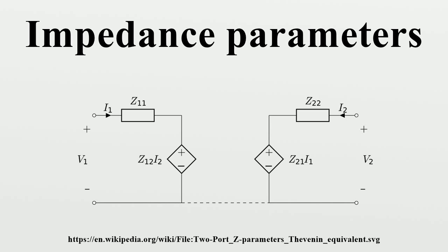For a generic multiport network definition, it is assumed that each of the ports is allocated an integer n ranging from 1 to N, where N is the total number of ports. For port n, the associated Z parameter definition is in terms of the port current I_n and port voltage V_n, respectively. For all ports, the voltages may be defined in terms of the Z parameter matrix and the currents by the following matrix equation, where Z is an N times N matrix, the elements of which can be indexed using conventional matrix notation. In general, the elements of the Z parameter matrix are complex numbers and functions of frequency.